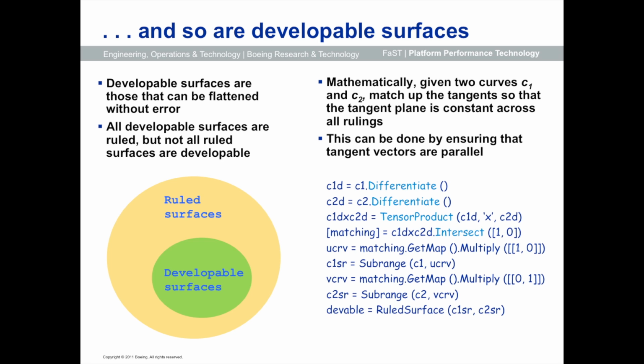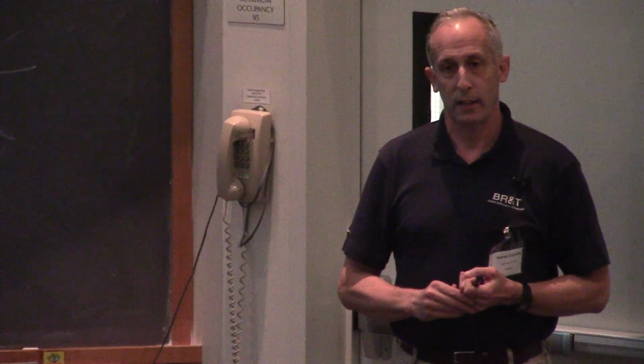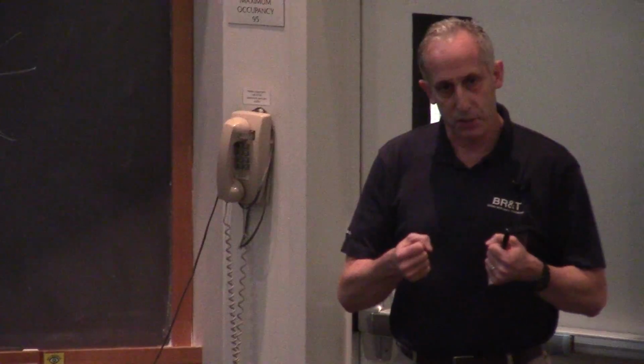Developable surfaces. Let's take a look. This is a somewhat more interesting example here. Suppose that I've got a manufacturing operation, and I want to make sure that what I am modeling is a developable surface. A developable surface is one which has 0 Gauss curvature, so I can flatten it out. So you can imagine if what you are doing is bending something out of a pretty stiff sheet of aluminum, you want to be able to make sure that the shape that you're bending it into is